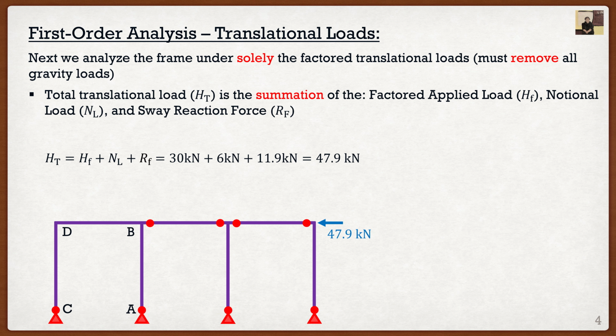So this is the analysis we are going to conduct. Remember, there is no gravity loads in this case. It is purely just a lateral load analysis. And even though it's shown here, I also want to emphasize there is no lateral roller that we had in the gravity analysis. We want our frame to sway in this case. We will actually want to determine how much our frame is going to sway. So of course, we are not going to restrict it from moving laterally like in the previous analysis.